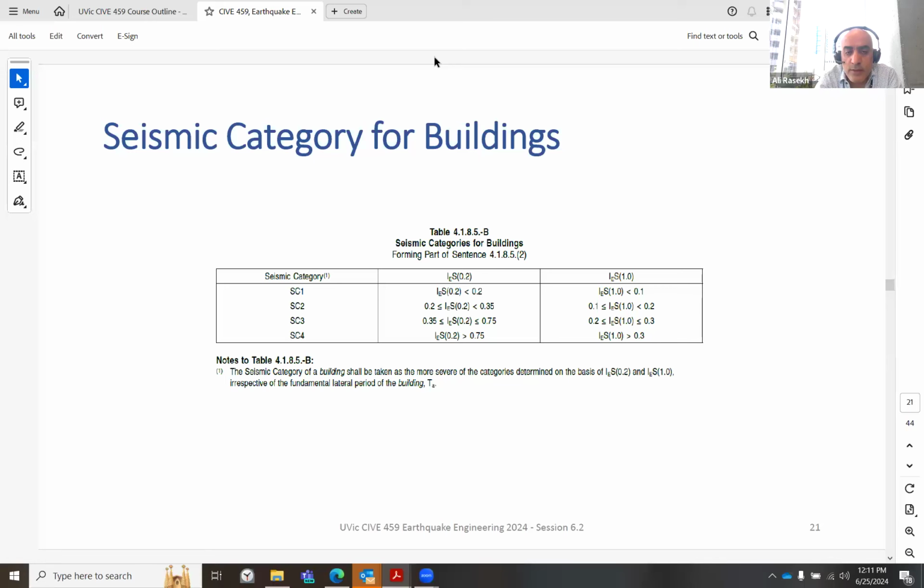I think I can guess, because the code emphasizes that you keep your vertical design separate from your lateral design. And then any engineer says, okay, I have a moment resisting frame. They are the same. I think the code means conceptually keep them separate, like design that frame for your vertical load and seismic load, and the combination of the two. Normally we use the load combination. So I see it as more conceptual, especially in the moment resisting frame.